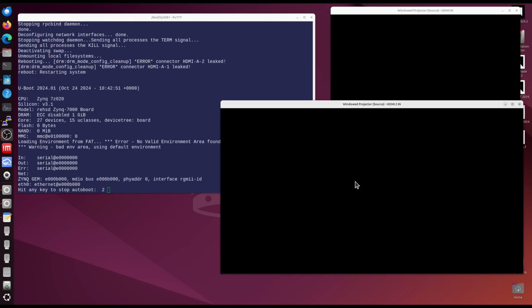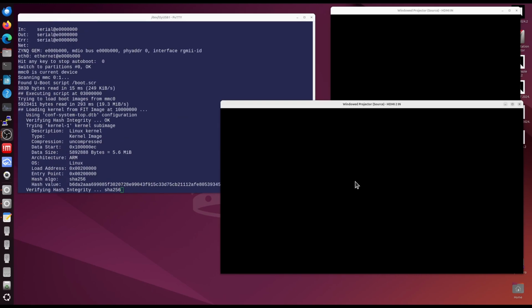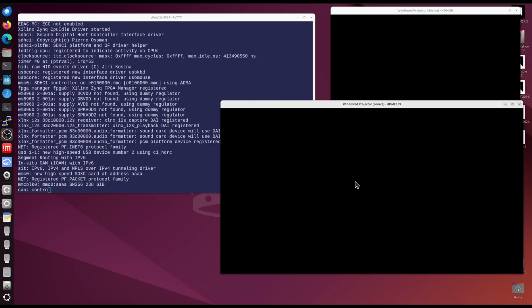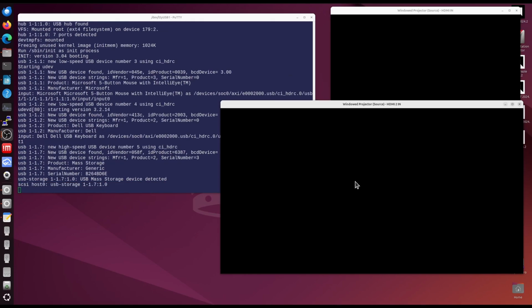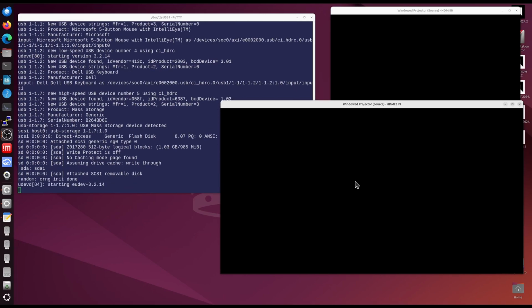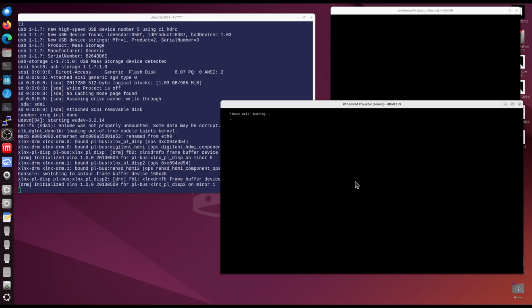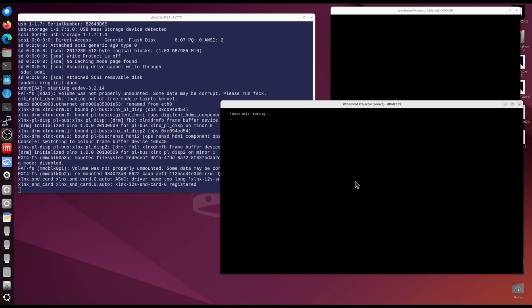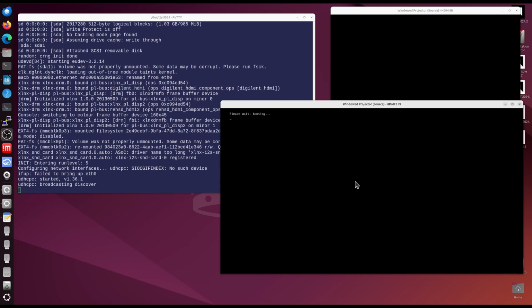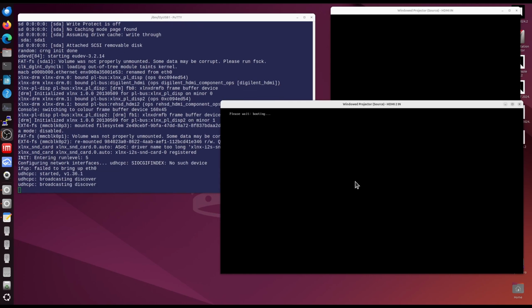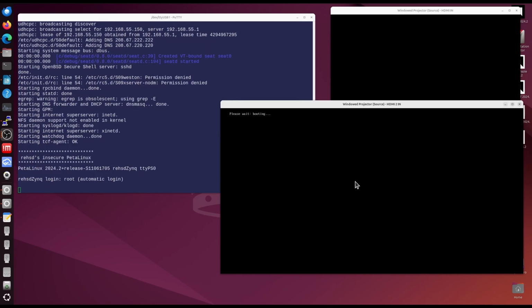If I don't try to load the X11, Xorg stuff, I see one behavior. If I don't try to load either of the graphical environments, I see a different behavior. And so that just tells me that maybe it's not all in Vivado that I need to do some fixes. There could be some coding things or PetaLinux things, DTSI things, something that I haven't tracked down yet.